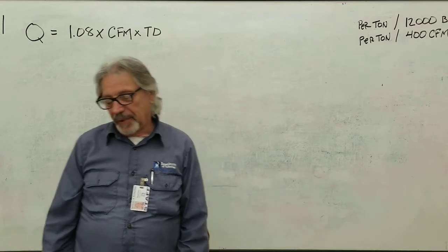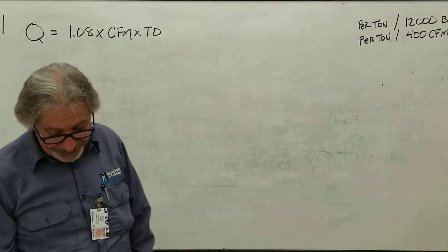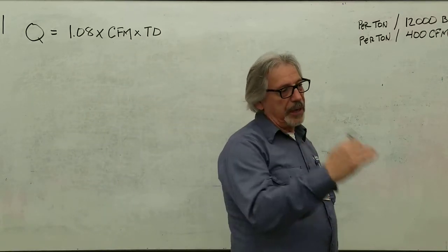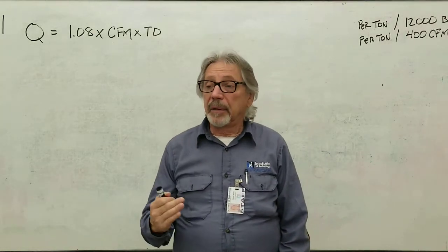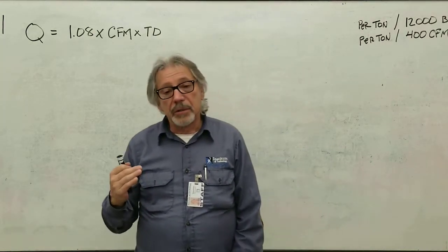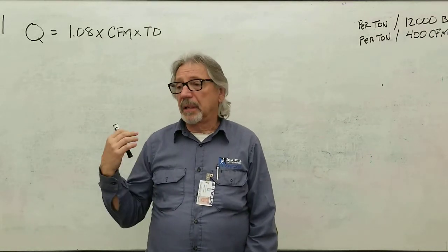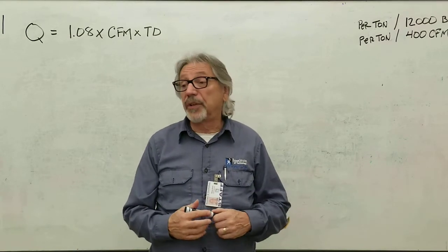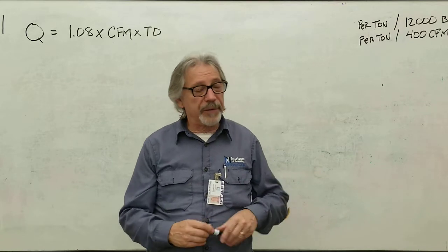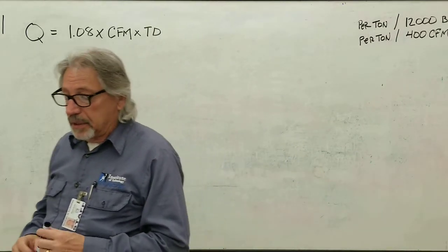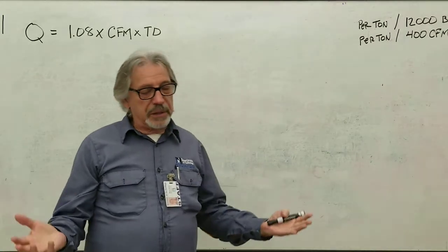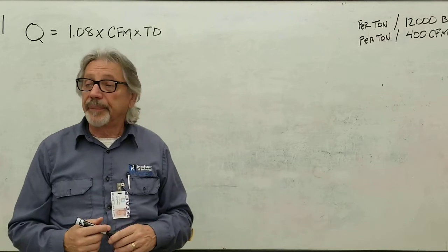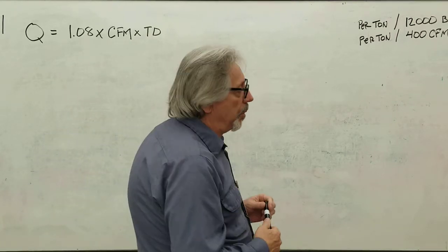No, no. The more velocity, as air increases velocity, it has a tendency to cool down warm air. So with high velocity and more movement, the air tends to get cooler. It feels colder because you have more draft. So they slow the fan down, so it just enters the room without anybody noticing, okay?